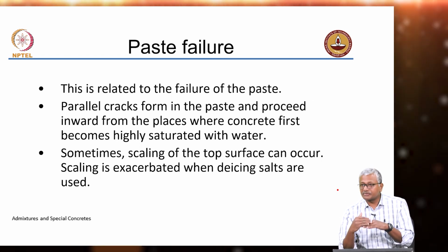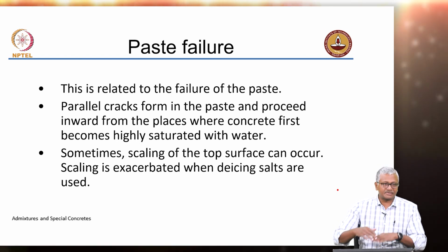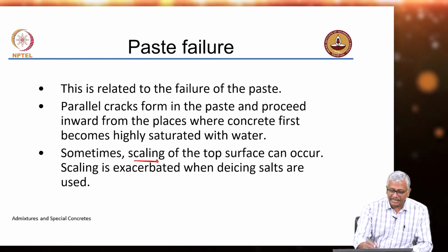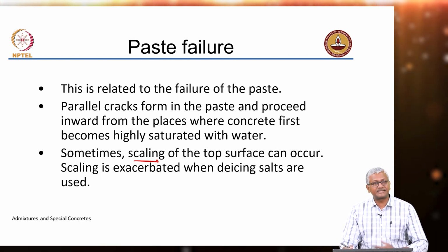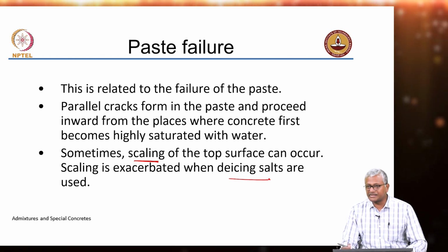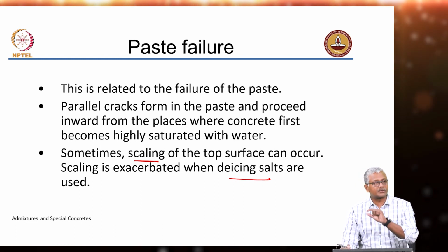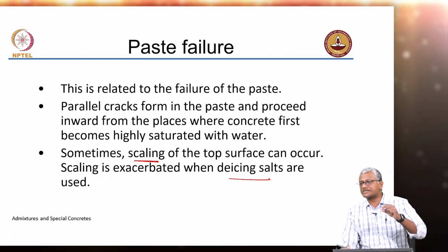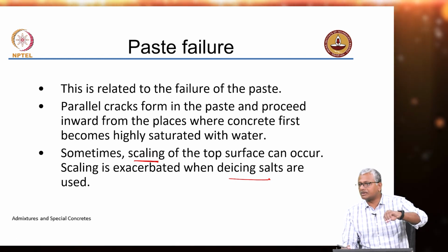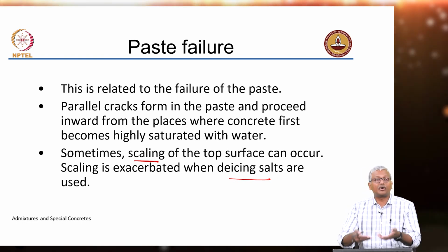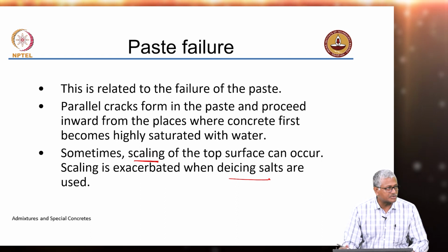So, because of this ice formation on the top surface, you may also additionally get, apart from freezing and thawing, scaling damage, and this scaling damage becomes worse when de-icing salts are used. It is interesting because de-icing salts are used to reduce the formation of ice. But because of the osmosis that happens of these salts into the concrete and the resultant crystallization of these salts, you can actually cause more and more scaling when the salts are used.